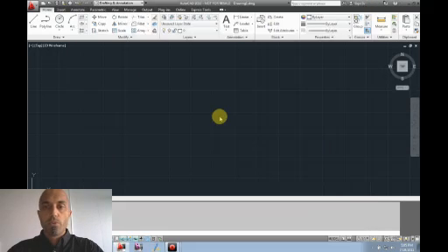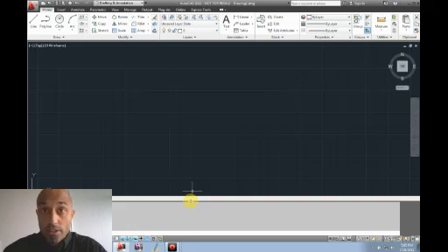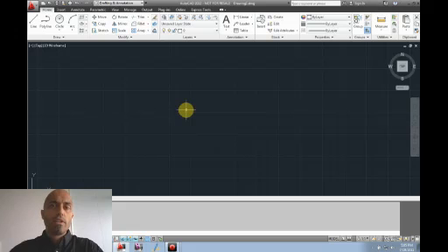So I won't go into more depth at this stage around that, but there is another trick that I've been using since I first started working with AutoCAD, and that's working with something called the PGP file. This really allows you to customize AutoCAD, not so much at the UI level in terms of the ribbons and toolbars that you have available, but just to enable commands to be typed in much more quickly.